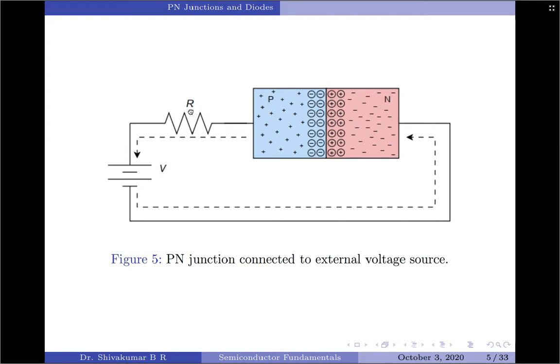The precise value of this depends upon the material that is used. For silicon devices, the barrier potential is usually estimated at around 0.7 volts. For germanium devices, it is closer to 0.3 volts, while LEDs may exhibit barrier potentials in the vicinity of 1.5 to 3 volts, partly depending upon the color.